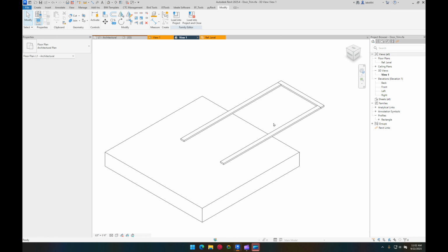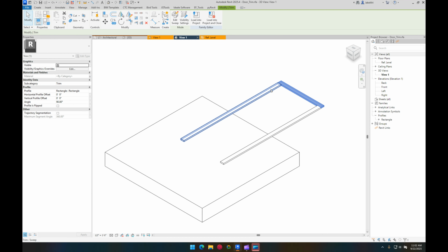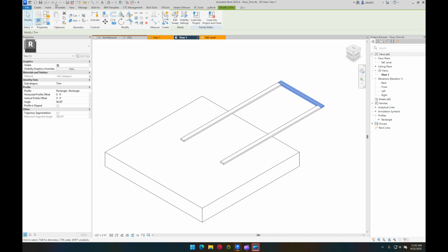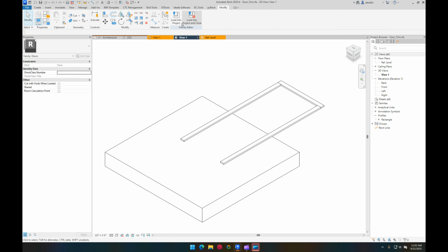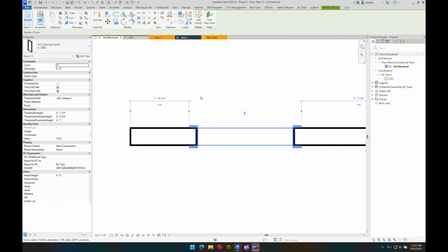That's awesome. One thing to take into account when you are dealing with this is if you have these objects joined, both these objects will inherit the same view. Even if they are modeled separately, Revit will then assign the same visibility override. So you can see that is set to on, and this is also set to on, which is not what we had before. So if we unjoin those, you can see they are independently different. All right, there we go. So now, since that's already loaded into here, we can see now, cool, everything is looking correctly.